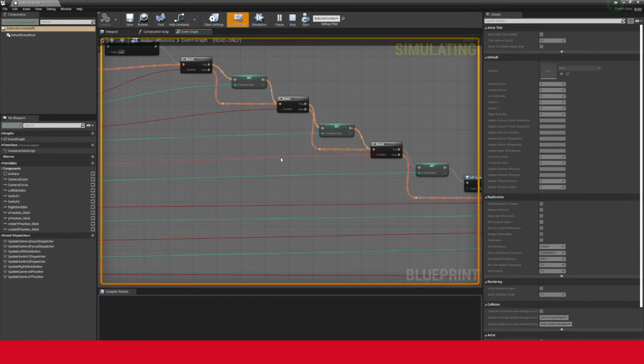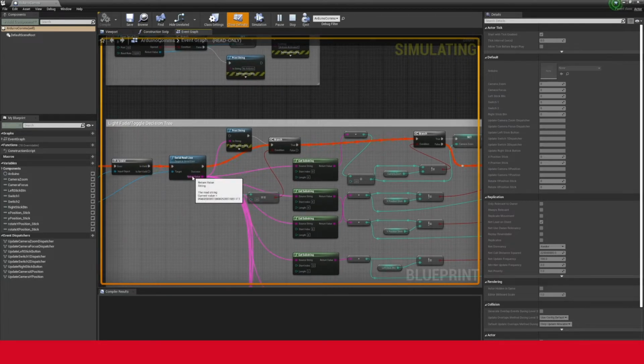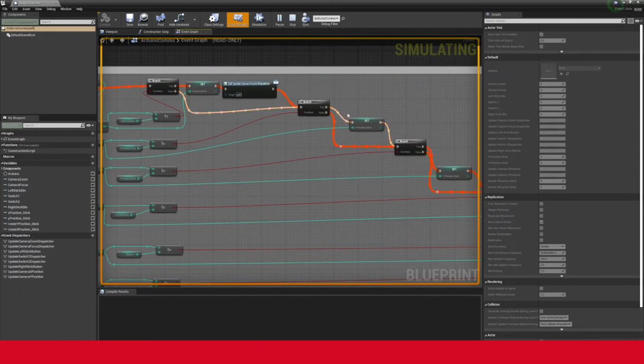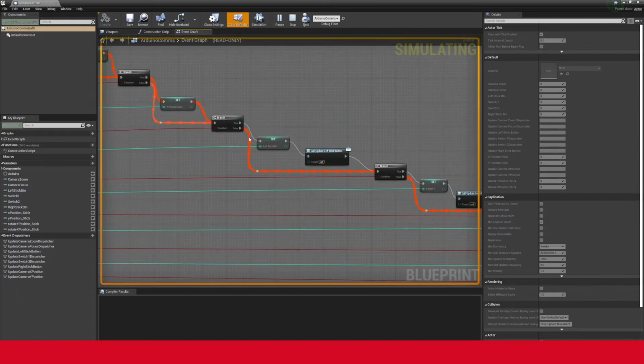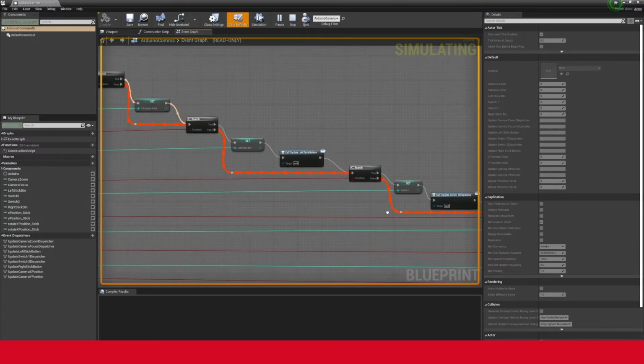You can see that some of these values are a little bit sensitive. So if you go to the actual return value, some values are just kind of tweaking out a little bit, and they just toggle between two values. We've tried to smooth that out using capacitors on the board, but it's not 100% working. But it's minor, right? So each of these go down, they check to see if the buttons are on or off. You can see the buttons are being toggled on and off. And then what they do is they trigger something in the main sketch.